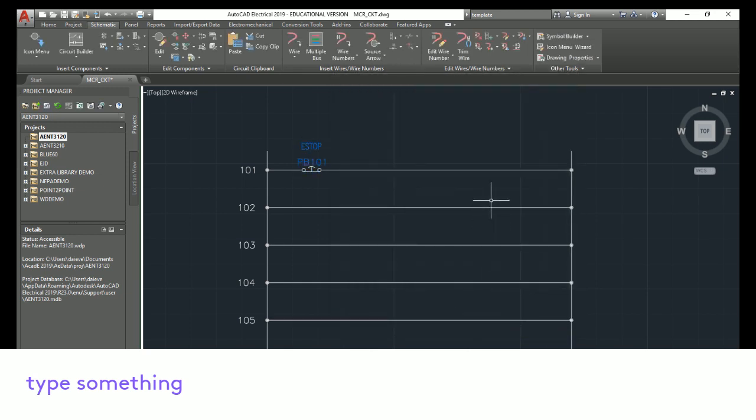Now, let's talk a little bit about some of the things we can do from here. The first thing I want to talk about: I've got a ladder in here, but I do have some drafting settings that I can use. Down here in the drafting settings, you'll see you can turn the grid off and on. So I can either have the grid in the background or not. Right next to that is a feature that's important to know about. This is called the snap mode, and you'll see that it's toggled with F9. I'm going to talk about that F9 snap mode in just a minute. But before I do, I want to show you guys the marking menu.